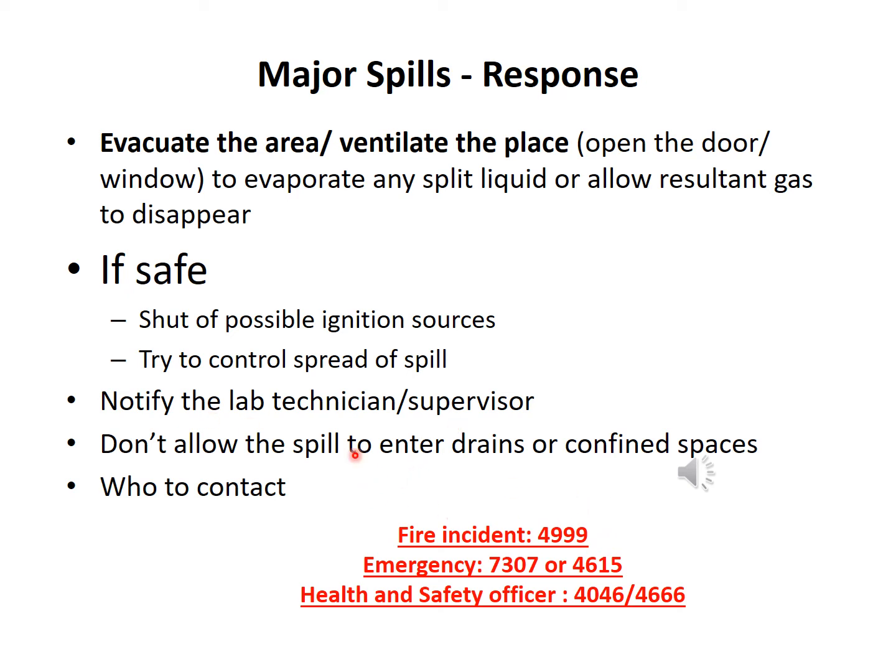and immediately talk to your technician or supervisor. And this is a very important step: don't allow the spill to enter drains or confined spaces. This is really very important. If the spillage happens close to the drains, immediately do something to stop it. And to whom to contact? If your technician or supervisors are available, they will contact